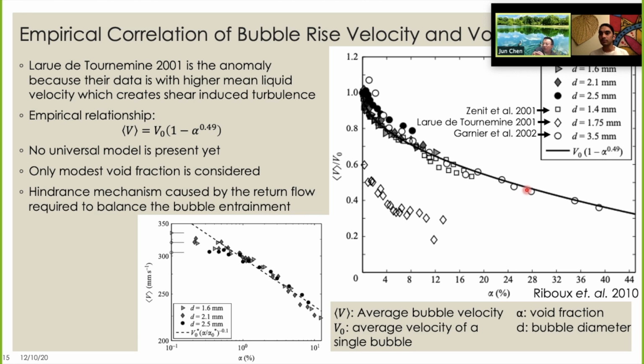Pranav, I think Drew's question is that if the particles are too dense, can you still do the planar PIV? If the PIV particles are too dense? No, the bubbles. That presents a threshold on the maximum void fraction you can go to.